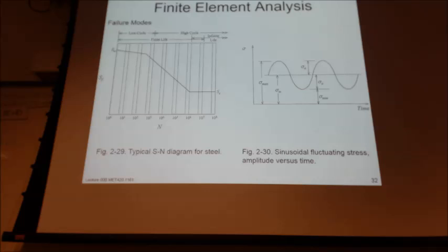So when we're applying fatigue loading to ductile materials, the basic structural changes that occur, and in this order, are you're going to have a crack initiation, then localized crack growth. The crack growth then goes into a high tensile area, and the crack proceeds across the section and begins to propagate. And then you have ultimate ductile failure when the crack just ruptures.